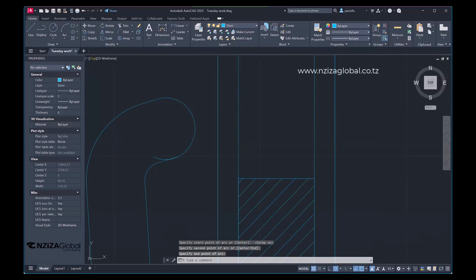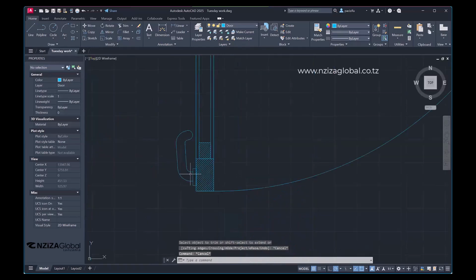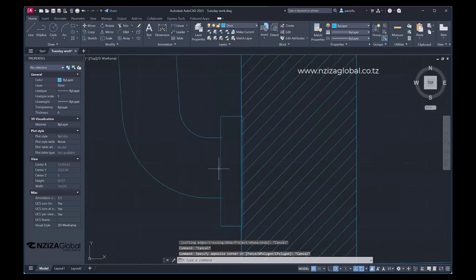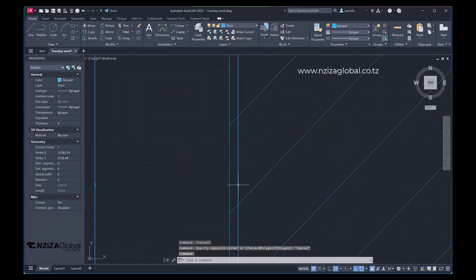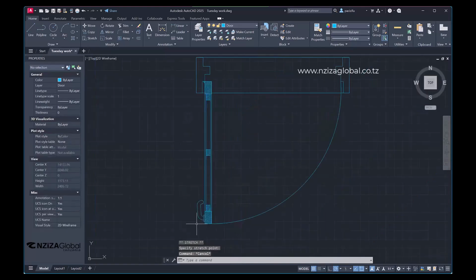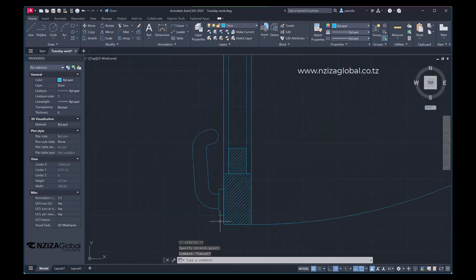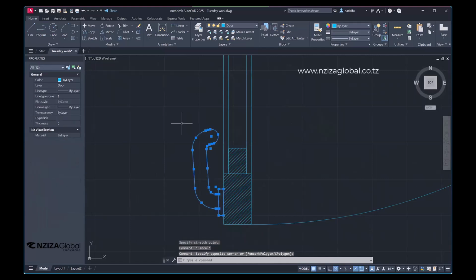So yeah. Take this back here. Then I can select the whole handle, then make a mirror in the center of this frame. Then I keep the copy.